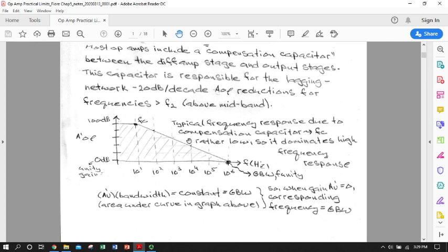And in fact, that was one of those cases where we swapped some of the gain from the open loop condition to the lower gain of a closed loop, but we got something for it. We got a bigger bandwidth. We're back to that concept. Okay, what if we did that to an extreme and we pushed our mid-band gain all the way down to 0 decibels, or 1?